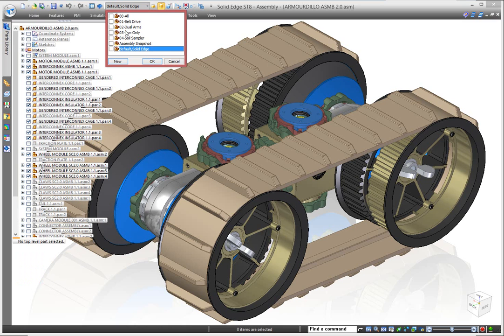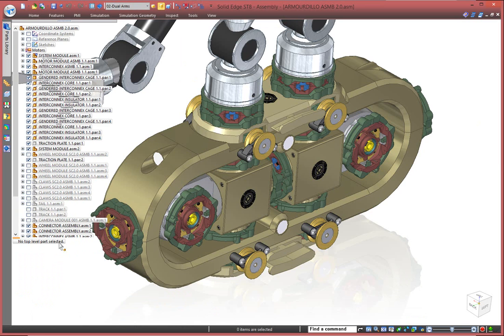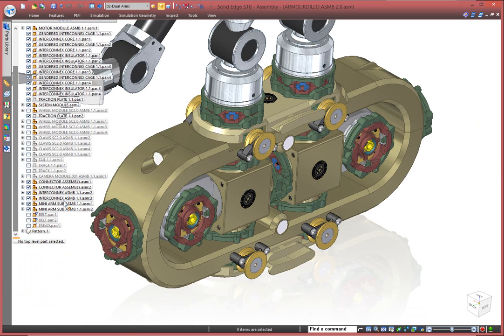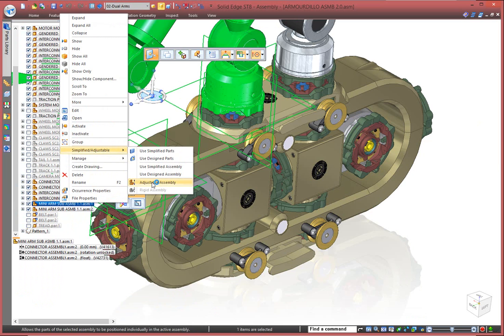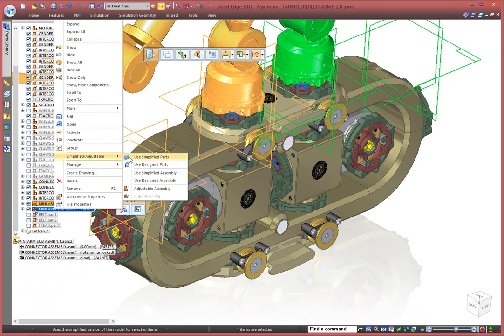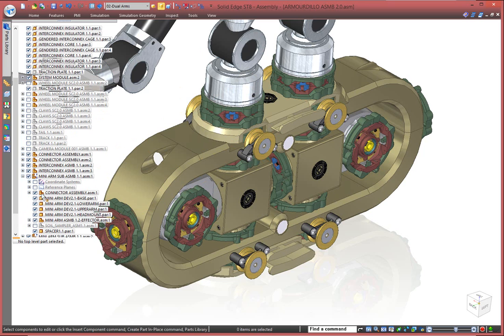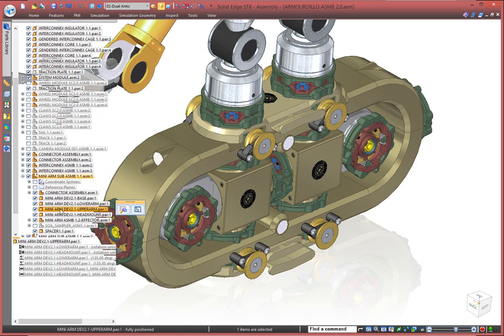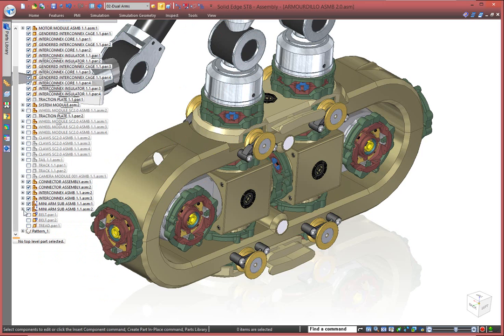You've seen how easy it is to drive components from the variable table, but let's take a look at another new capability offered to help you promote and use adjustable assemblies. As we change our focus to the top of the robot, you'll notice we've placed two of the same mini-arm sub-assemblies. Once made adjustable, we now have the option to override relationships, which basically moves the selected relationship to the top level assembly, giving us full control over these relationships.